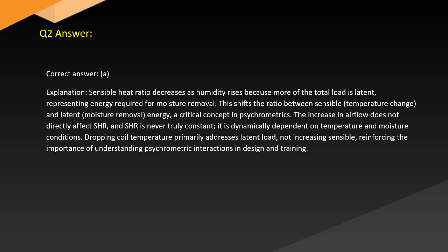The increase in airflow does not directly affect SHR, and SHR is never truly constant. It is dynamically dependent on temperature and moisture conditions. Dropping coil temperature primarily addresses latent load, not increasing sensible, reinforcing the importance of understanding psychrometric interactions in design and training.